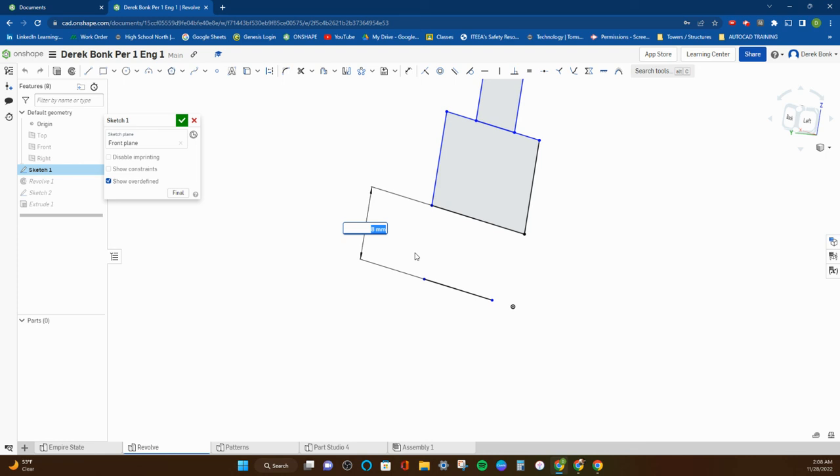My tolerance is the size to make the steel work. You can't make something exactly the same dimension. If I had a 16mm steel rod, you can't print something exactly 16mm and expect it to fit. You need a little bit of clearance, or what's called tolerance. 0.3mm is what I go for in terms of a good tight friction fit type tolerance.